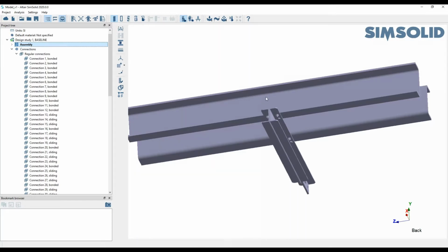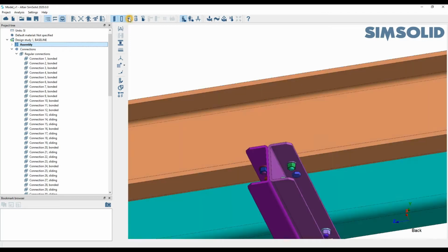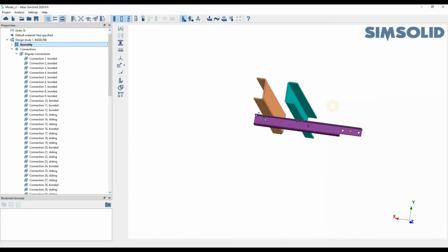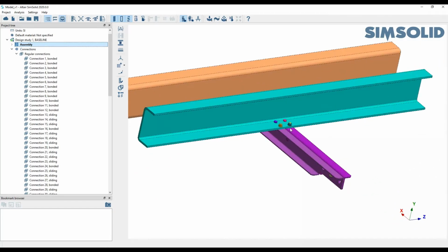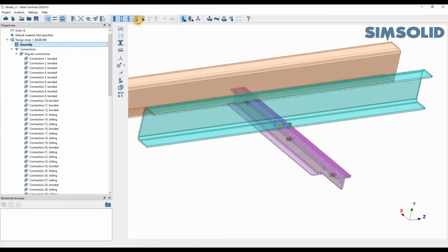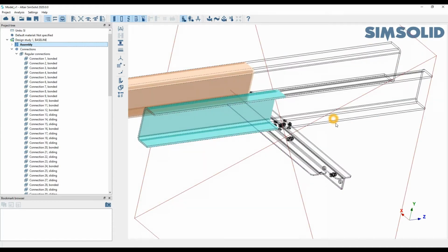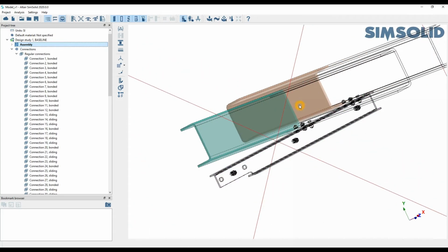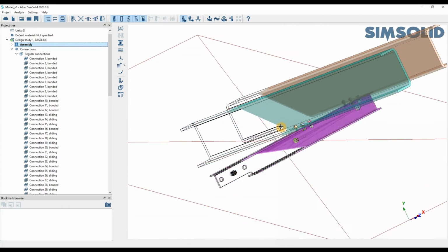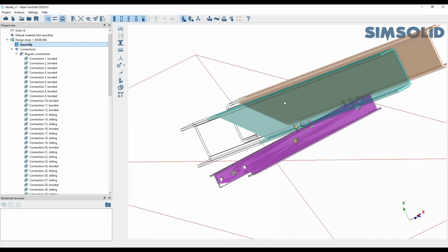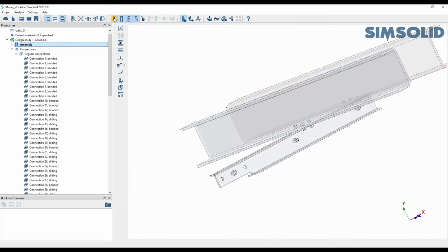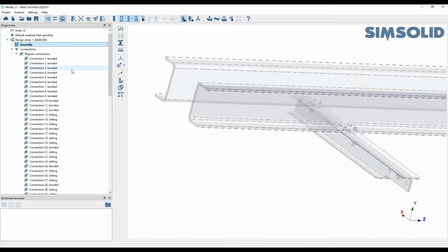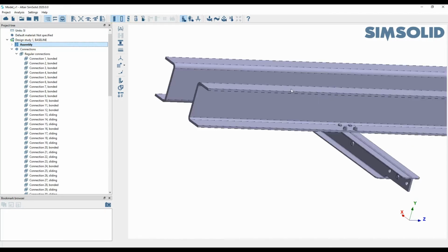Along the rest of this bar here, you have all of the different visualization tools that you need to see your different parts. You can make it a wireframe, so you're looking at the edges. You can specify all your parts in different colors, so you know exactly where they are. You can make them transparent, and you can also implement a cut cross section through it. So you can see through it all, and you can rotate it around to reach other areas.